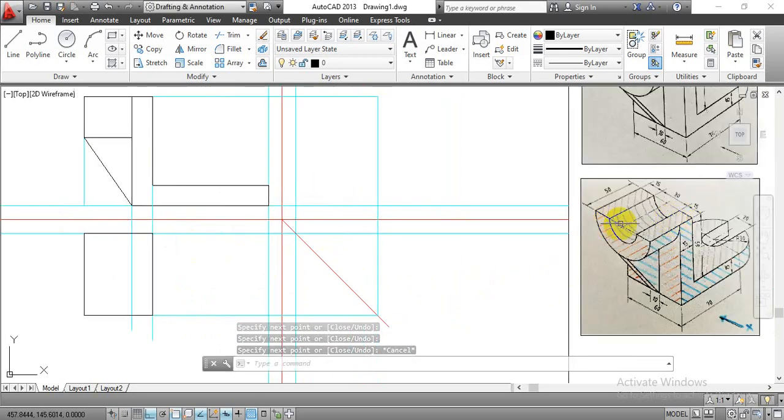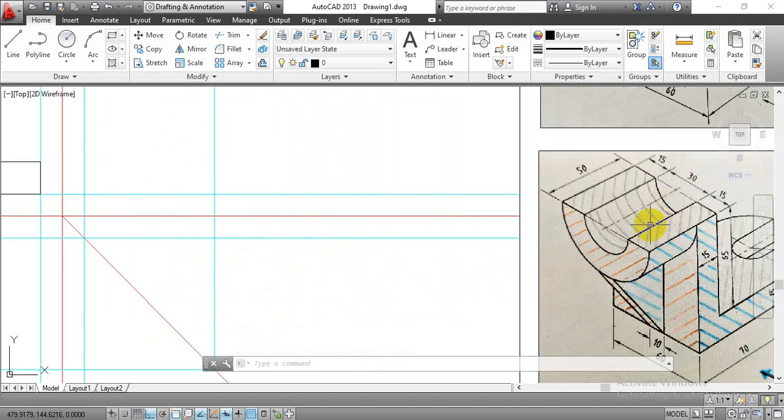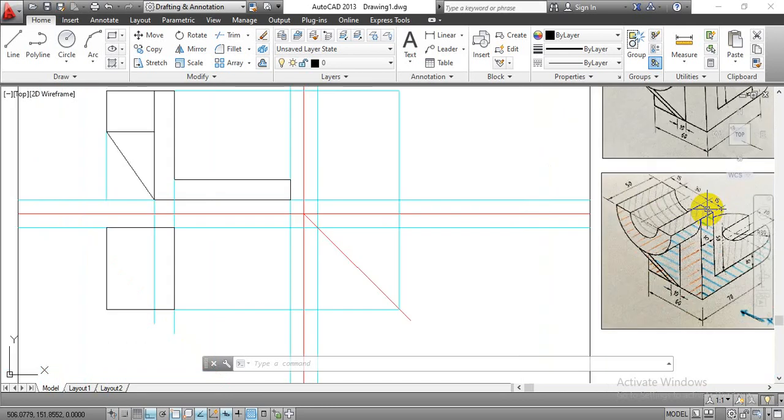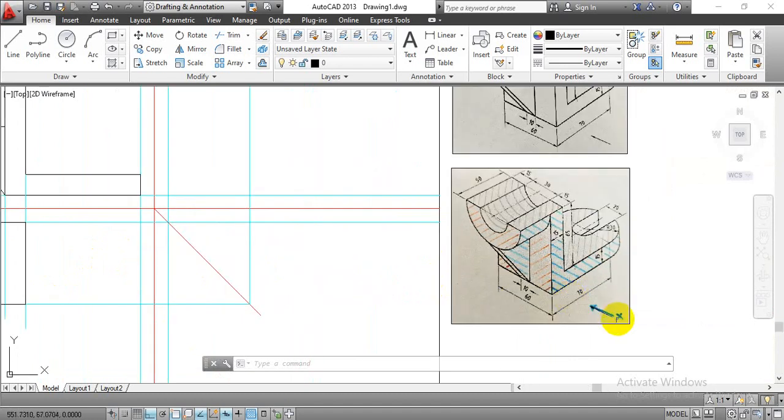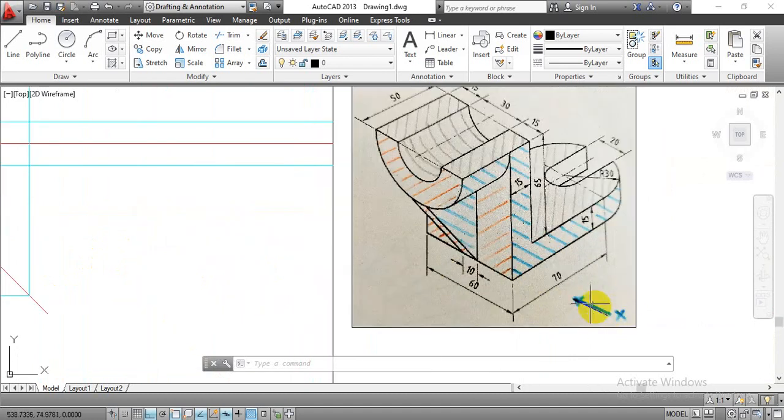In that we are going to draw horizontal line at a distance of 15 mm, again from this corner 15 mm. So to understand this top view projection, you can imagine in such a way that if the observer direction is like this, okay, so this extreme far point or the far line at the top end is nothing but the starting line in a top view projection.